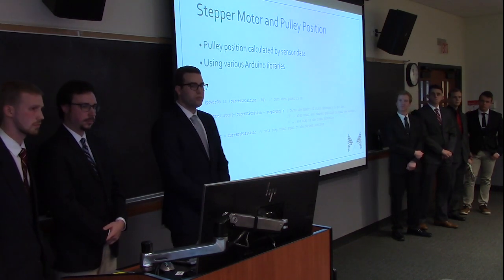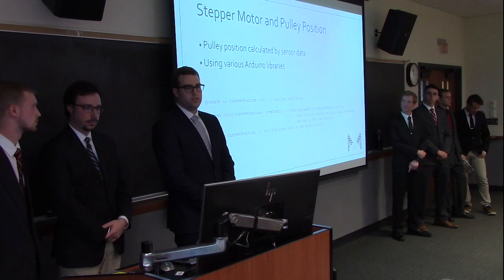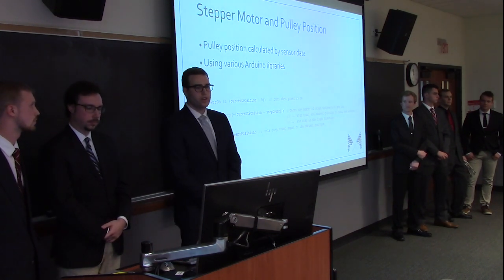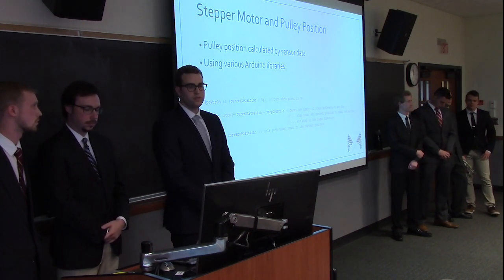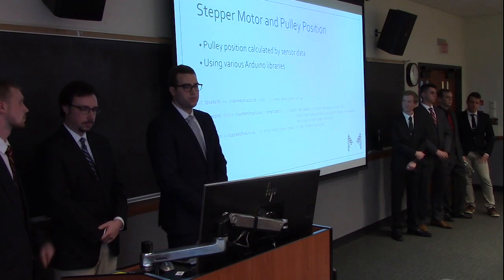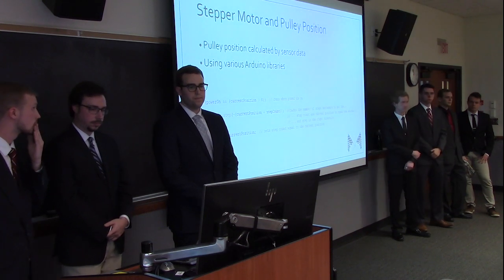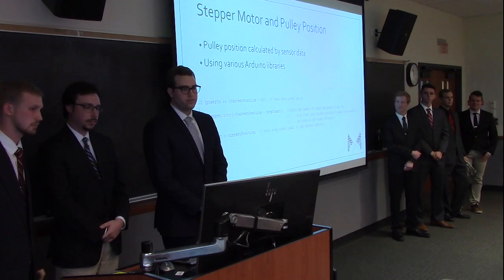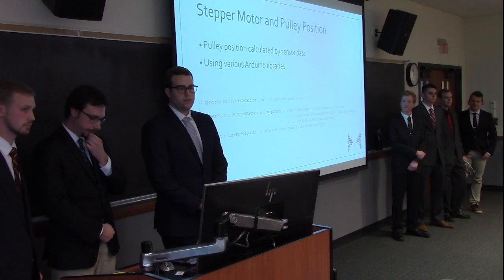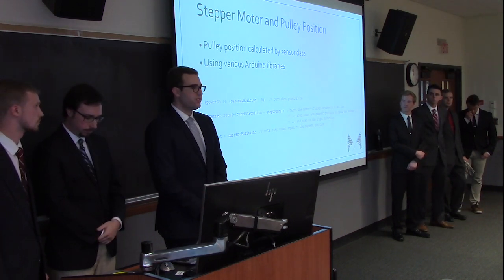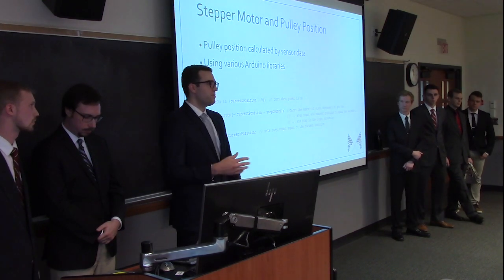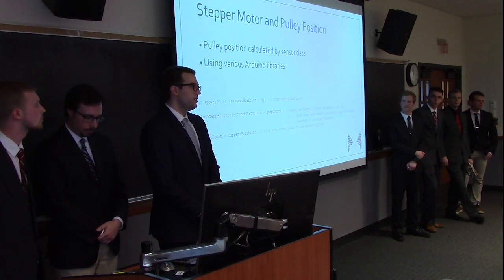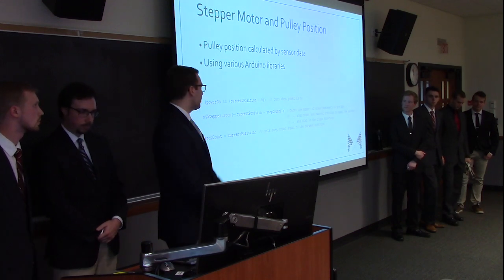And finally, we have the stepper motor. The stepper motor is driven by data gathered from the sensor array on the car, and it directly correlates to the pulley position on the pulley sheaves. This code here shows a step function that simply increases or decreases the motor position relative to itself. And one of the challenges of this project was processing the data fast enough to keep up with the rapidly changing condition of the vehicle. Now I'll let Matt talk about the mechanical actuation.